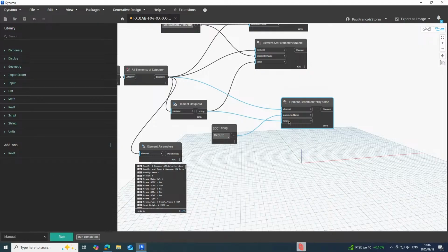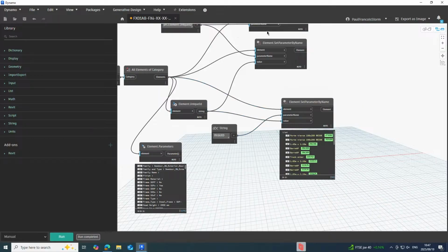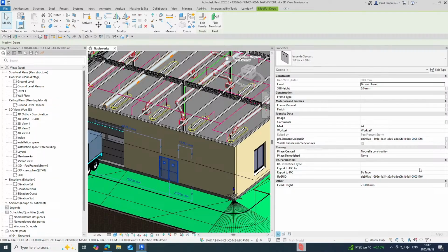Save and run it. And there it would have written the item through to there. So we'll probably find now that the IFC GUID is exactly the same as the Revit ID. So if we had to convert this to an IFC file, then the IFC GUID would still be the same as the Revit GUID. And this is a unique identifier. The chances that anything else on the planet is called by the same GUID is actually very slim. So that's why we use them, and they're identifiers.